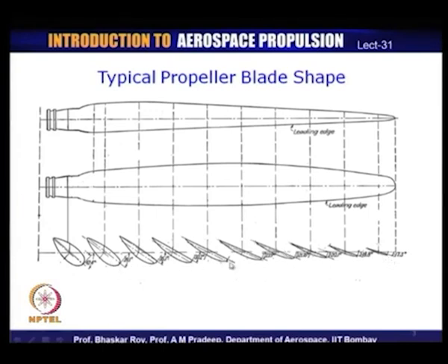So, that is the change of the angular setting of each and every propeller aerofoil, and the aerofoils now become what we call finer and finer setting. So, the root of the propeller is set at what can be called a coarse setting, and the tip of the propeller is typically set at a fine setting. So, within the blade itself, the propeller aerofoil settings move from coarse setting to fine setting as it moves from root to the tip of the blade.